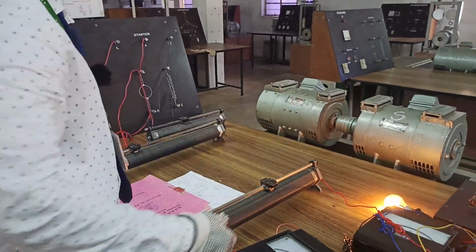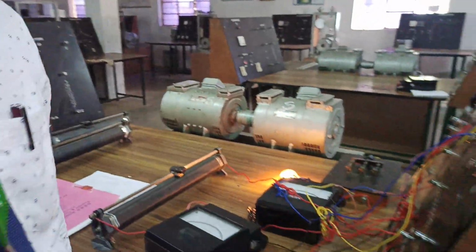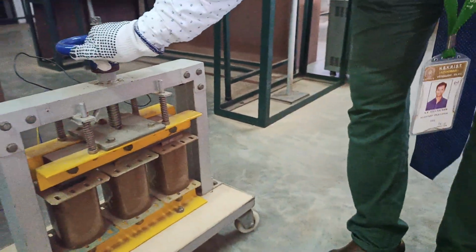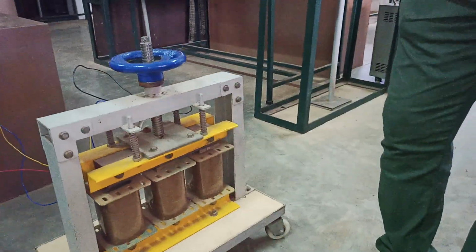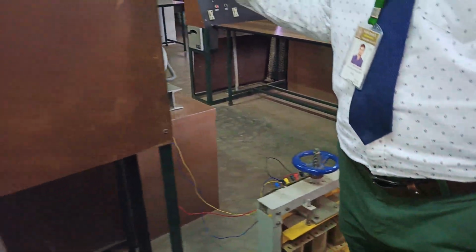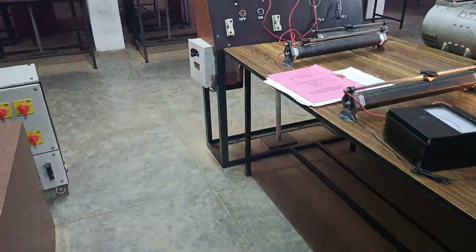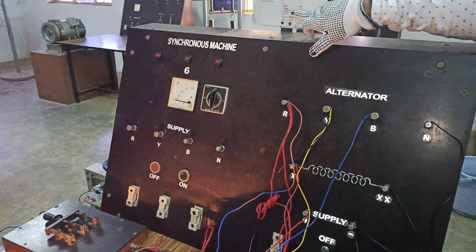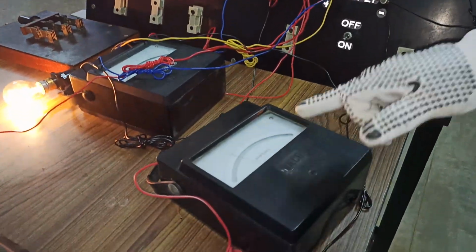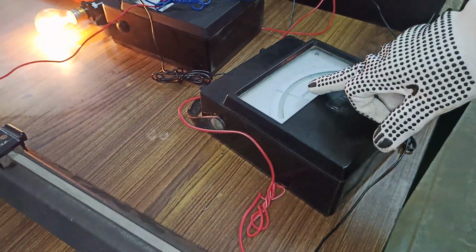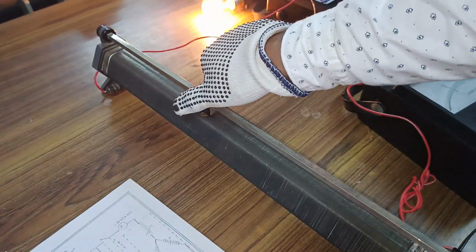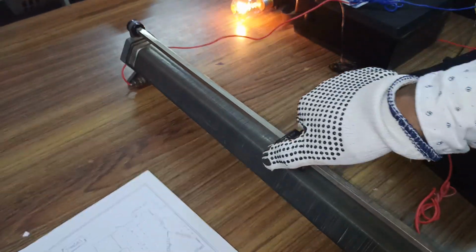This potential divider is set to a fixed value, and we have applied the maximum inductive load. So I had already applied the total inductive load. In this inductive load, when it was fully loaded, the short circuit current is around 4.33 amperes, and you have to write down the corresponding field current. Okay, so the corresponding field current is 0.3, and then we have to write down the voltage and slowly remove the